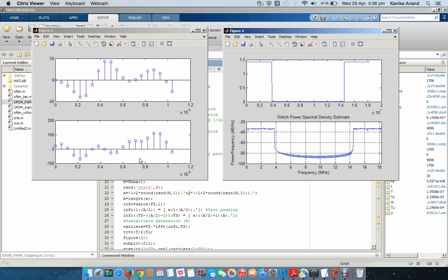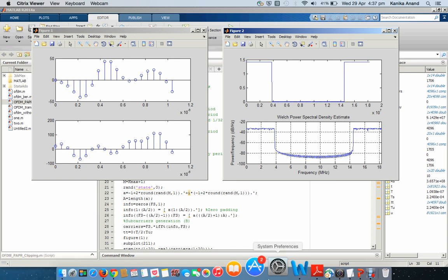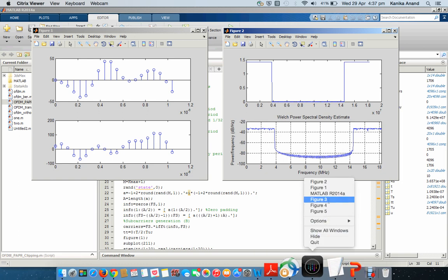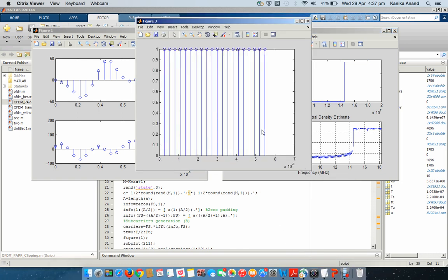this is the plot in the time and the frequency domains. We can notice that the carrier is the discrete time baseband signal. We could use this signal in baseband discrete time domain simulations. Now the first step is to produce a continuous time signal, to apply a transmit filter GT to the complex signal carrier. Now the output plot of the impulse response of the filter is here.